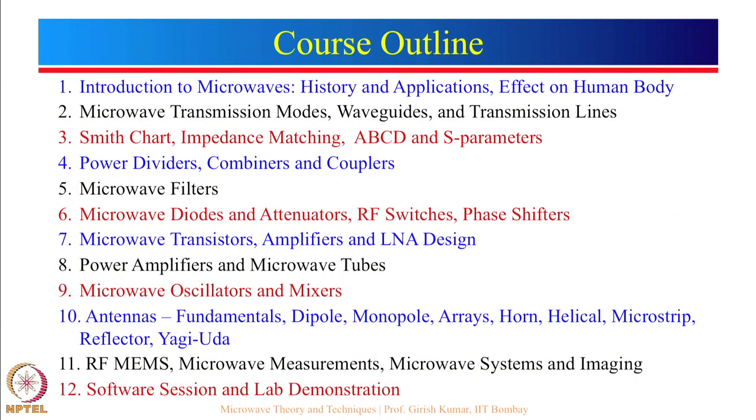And then we will talk about a very important concept of impedance matching techniques. We all know that for maximum power transfer, the load impedance should be equal to the source impedance, but that may not always be the case. So, this impedance matching network should be lossless so that maximum power transfer takes place to the load, or it could be an antenna.